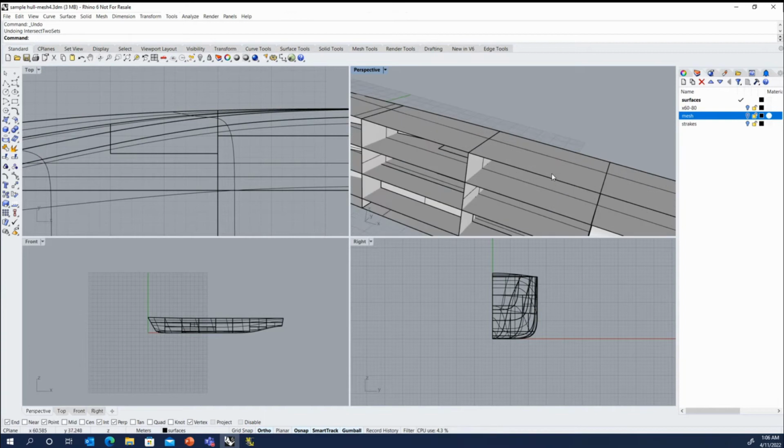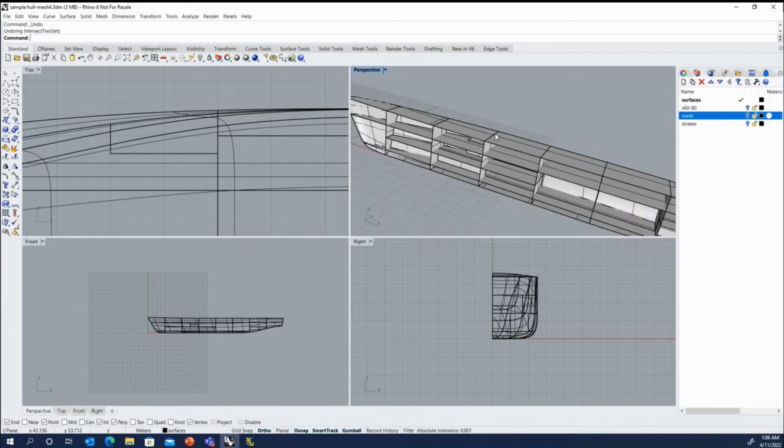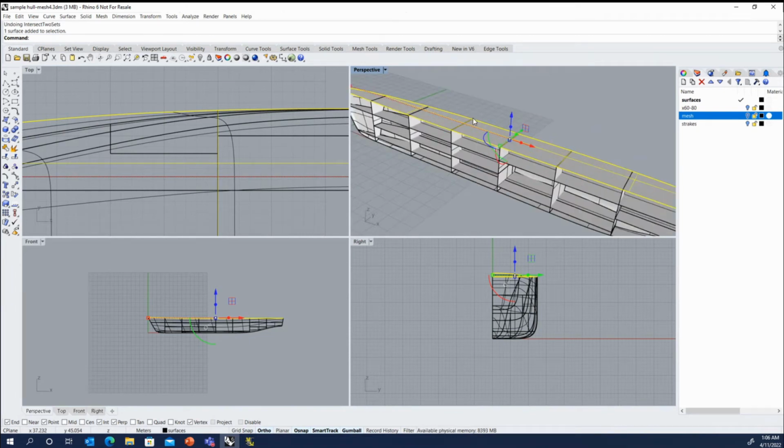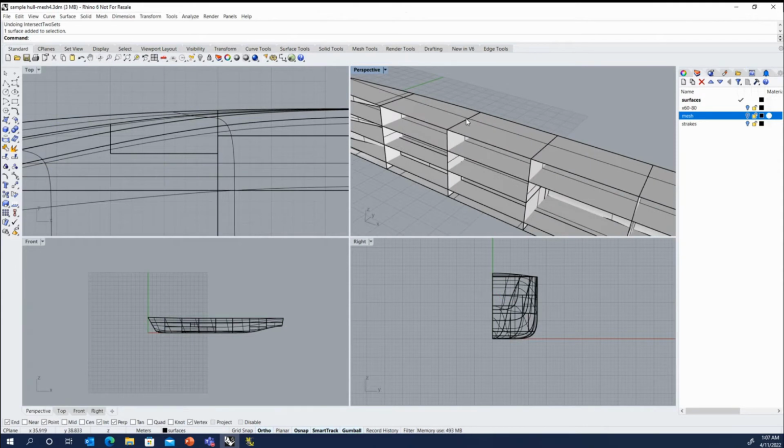For now, rather than creating all of those cutting planes, which is a lot of extra geometry, makes it difficult to see into the model, I tend to like using the contour command. Now, one advantage of using those planes and doing a manual intersection is that you have very good control over the spacing. So for that transverse spacing, if I actually did need 5 increments at 1 meter, then 4 increments at 0.844, and then 2 at 0.8125, and then a couple more at 1 meter, using those planes might be a good option. A little bit extra work, but you have very good control.